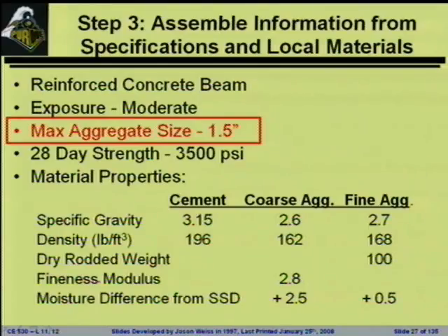All right, so typically in the types of problems that you will get for homework, since you're not necessarily familiar with the local markets of whatever the problem is that you're designing the concrete for, we will tell you what the size of the aggregate is. So step 3 goes fairly quickly. Here again, you're using the maximum size of the aggregate based on the distance in the forms and the distance between the reinforcing steel.